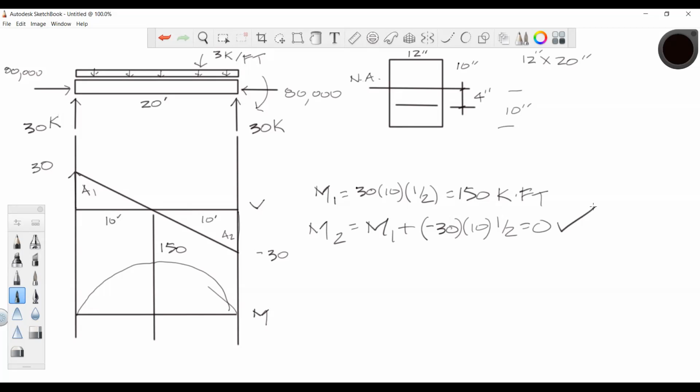It is. I mean, that's nothing new, right? Now, we haven't even looked at what's going on here yet with the cables below. We're going to get to that in a minute, okay? But we had to solve this to get what's going on in this beam. So we have a bending moment going like this. That's putting the top of that beam in compression and the bottom in tension, okay? Is everybody okay with that?